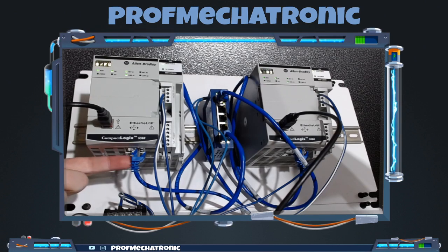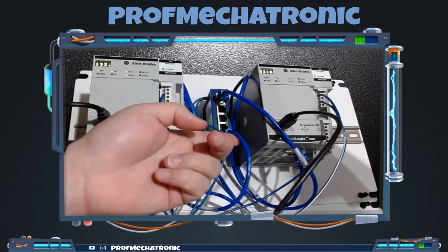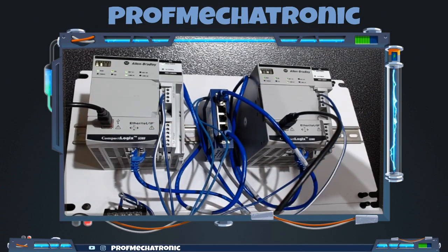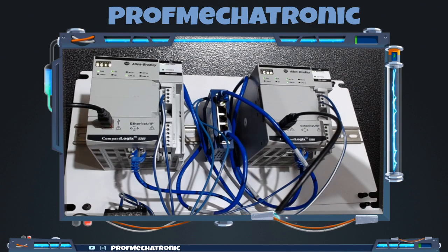Next up, you'll see that we have blue Ethernet cables. So these Ethernet cables are communicating and set up between the hubs themselves. You'll notice there's not a lot of lights flashing right now. We haven't done any configurations on our PLCs. So our PLCs aren't really set up to do any comms, and that's why you don't see any of our lights over here on our actual switch set up and flashing right now to show us that there's communication.